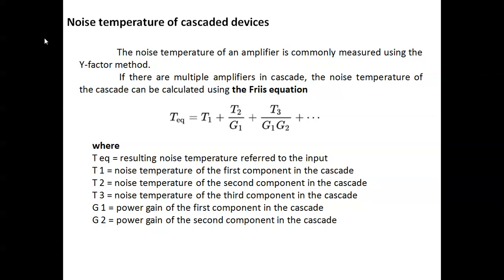If you want to calculate the noise power of one device, you go to the internal equations, like the equation we just saw for the noise temperature of a wireless communication system. But here it is more than one device, placed in a cascade manner. Then how can we calculate the noise power?